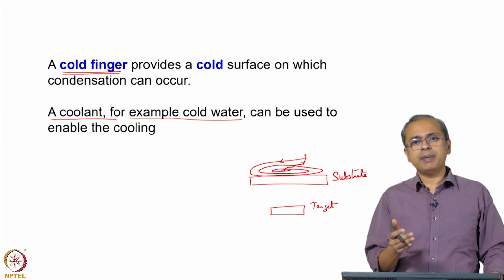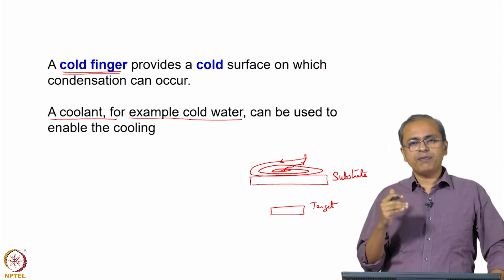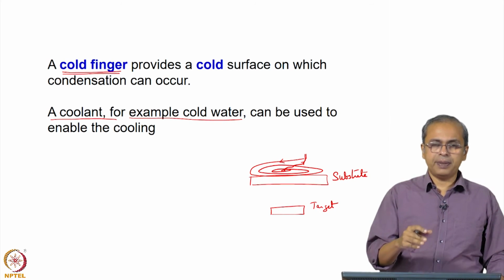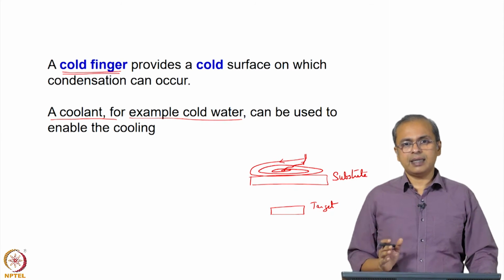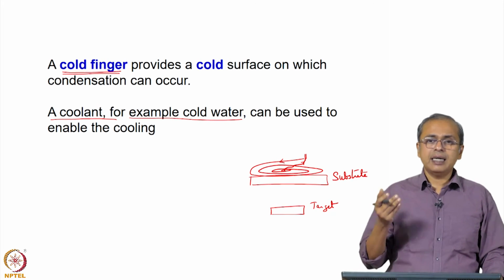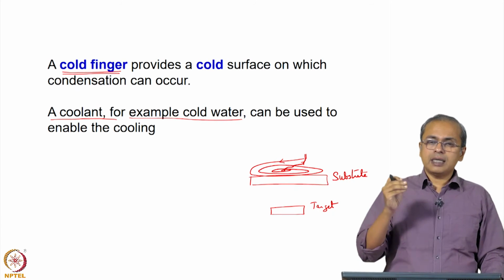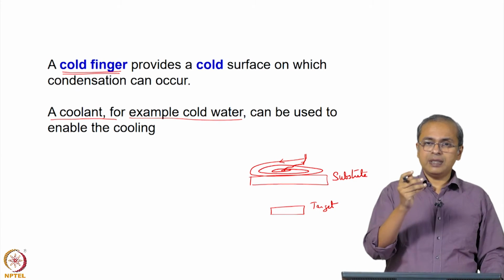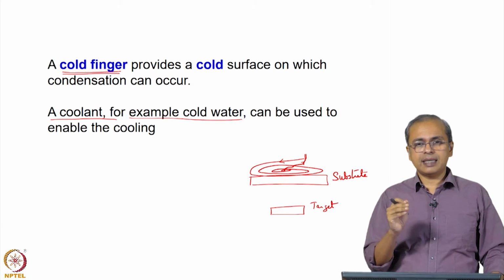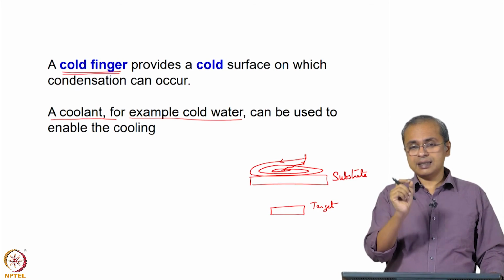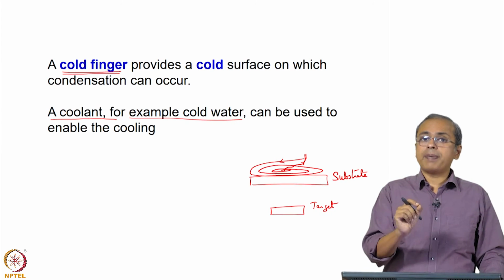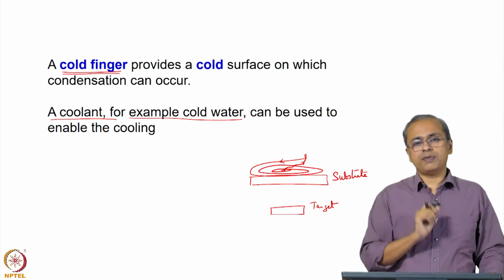More specifically, you can maintain the temperature, you can confidently say that all of the condensation happened at let us say 5 degrees centigrade, something like that. You can say that and you can maintain that. It is important because that impacts the extent of these nucleation and growth kinetics processes, and therefore it impacts the crystal size that you will get. It also impacts the distribution of crystal sizes that you get.